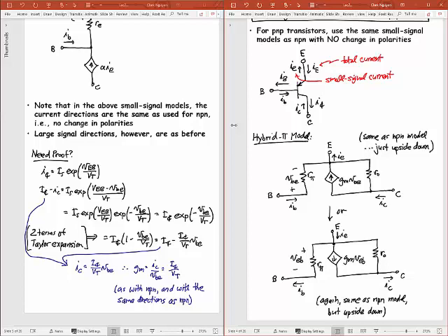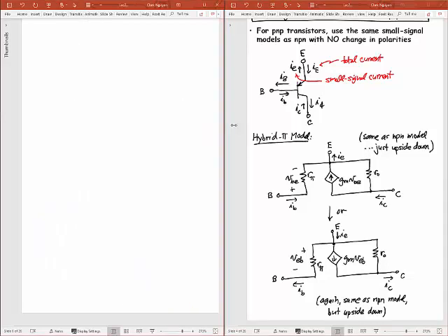All right, I'm going a little fast on this right now because I really want to get to NMOS transistors. I sort of did all of this in the last lecture, but now we've reached that point. We've reached NMOS transistors. So let me slow down a bit. And let me derive the small signal circuit for an NMOS transistor. This is the circuit you will replace the NMOS transistor with when you're doing a small signal analysis.